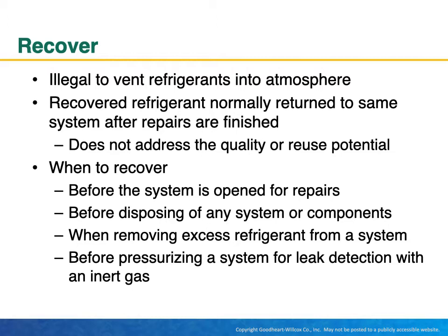When to recover: before the system is opened for repairs, before disposing of any system or components, when removing excess refrigerant from a system, before pressurizing a system for leak detection with an inert gas.